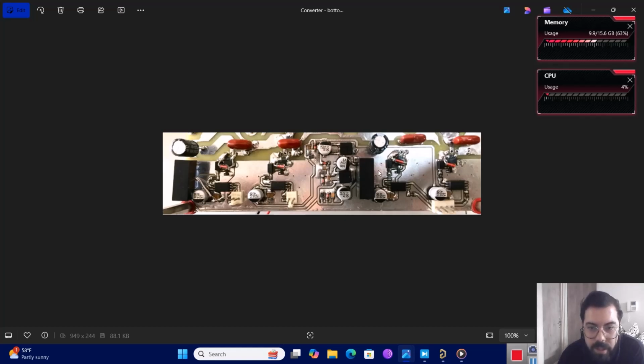And I have a circuit here. It's a power supply circuit for these gate driver circuits. Each regulator provides 12 volts and 5 volts for my gate drivers, and this 12 volts is going to be connected to these modules, because I have two floating switches, so I need to use an isolated power supply for that.